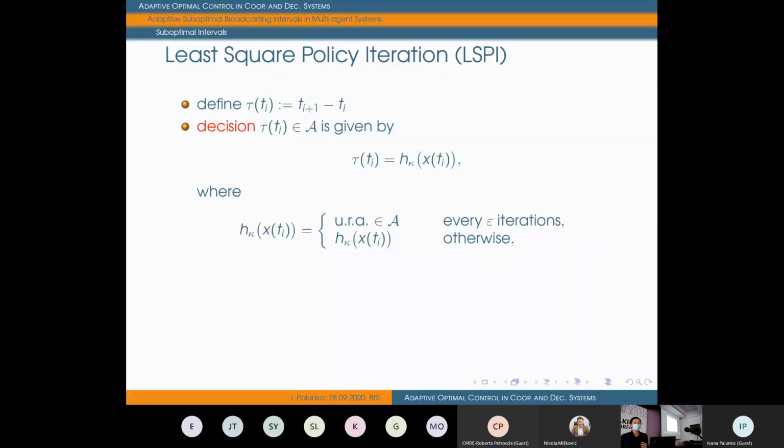Based on small gain theory, we have the upper bound on stability from 0 to some frequency, and in between is somewhere an optimal frequency for each, depending on the performance of the system. Because if you're hovering, you don't need to communicate all the time. If you're doing an aggressive maneuver, you need to sample more frequently. So that's the goal of the whole motivation.